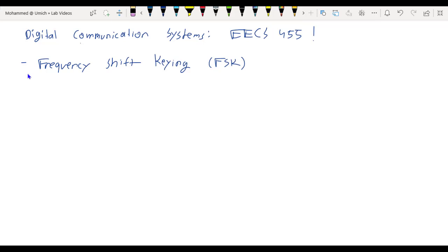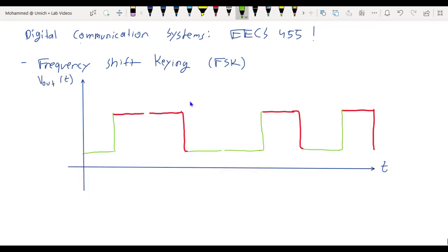Now, since the string of 8 binary bits is encoded as a sequence of 8 sinusoidal tones, you're going to use your frequency discriminator circuit to convert each sinusoidal tone into an output signal that's proportional to the corresponding frequency of the tone. And so a plot of the output of the frequency discriminator circuit might look something like this. Since a lower output corresponds to the binary digit 0, and the higher output corresponds to the binary digit 1, you can write down the binary string encoded in the audio file, and from that, you can convert it to base 10 to obtain the actual message.